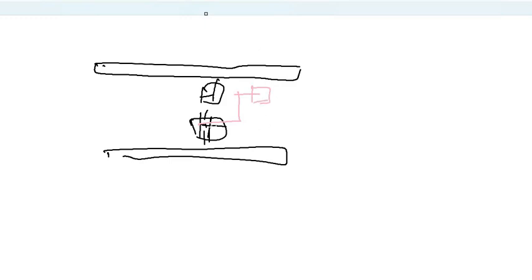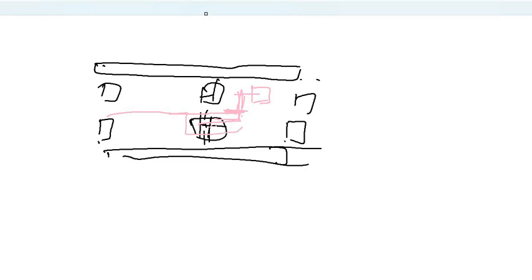Now there's another module here, another set of transistors. If I have to run a connection from this side to this side, this will block me over here. Because I have used my M2 vertically, it is blocking my routing over here. It will create a short. So what happens is I have to detour the signal and go around. This is not an efficient way of routing, or I might have to jump to another higher metal and go again. That is also not acceptable.